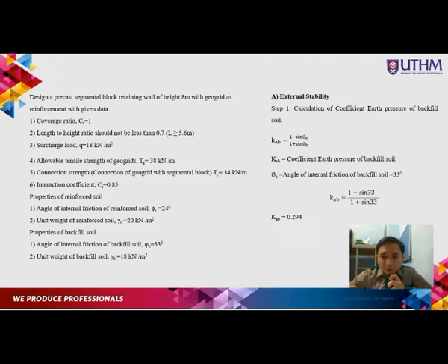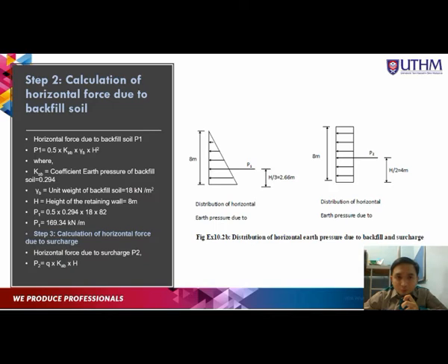The first step is to calculate the external stability. The first step is calculation of the coefficient of pressure. Then step 2 is calculation of horizontal force due to backfilling. So it's P1 and P2.